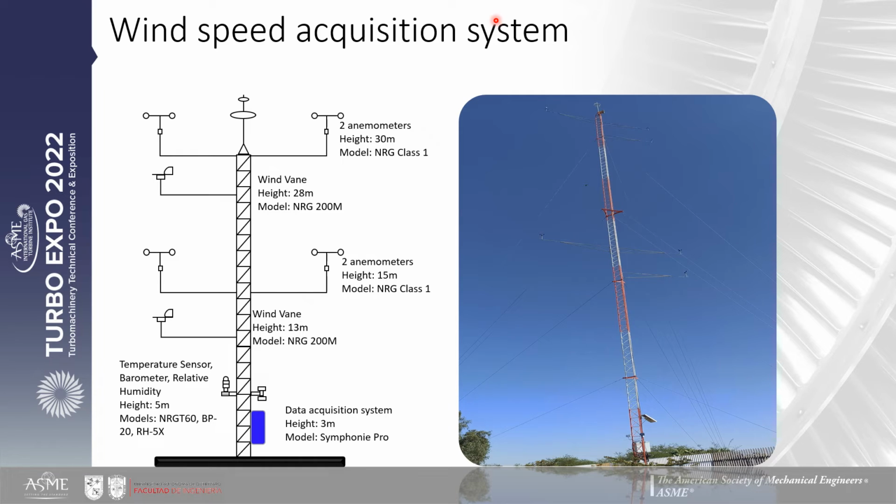According to the predominant wind that we found in the statistical analysis, from east to west, we must orient the arms of the anemometers to the north and south for a correct acquisition of the velocities.